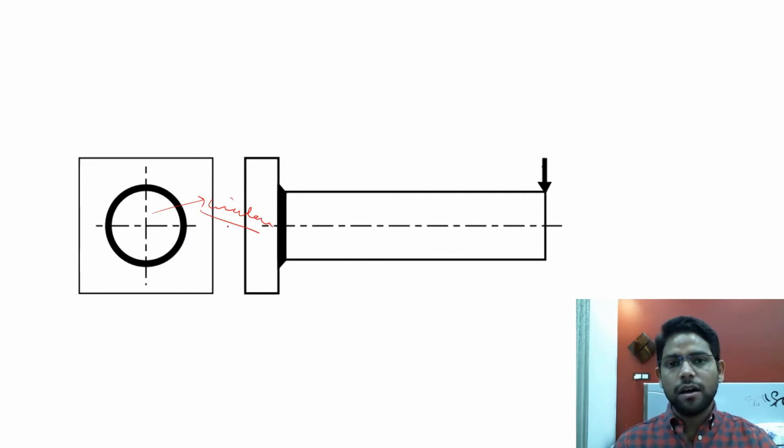Now since the cross-sectional area of the beam is circular, the weld is basically in the shape of a ring. Now you need to know how to calculate the second moment of area of a ring.